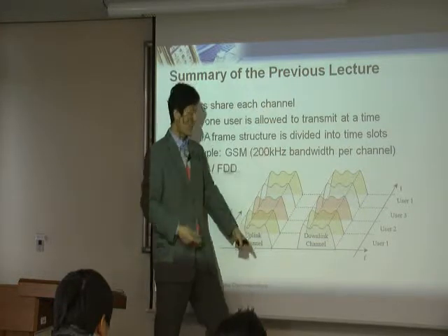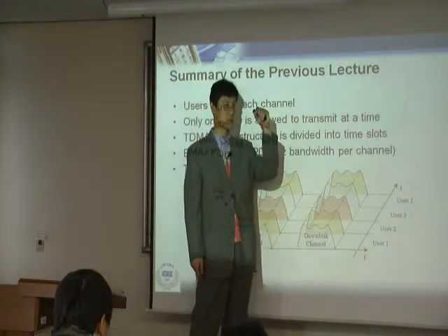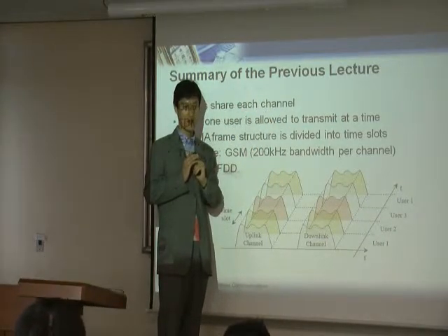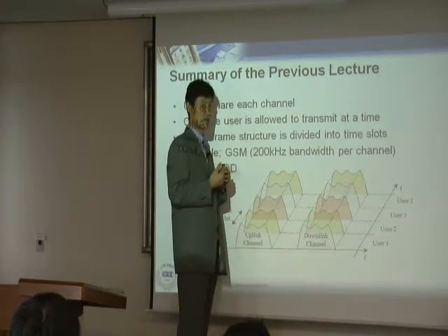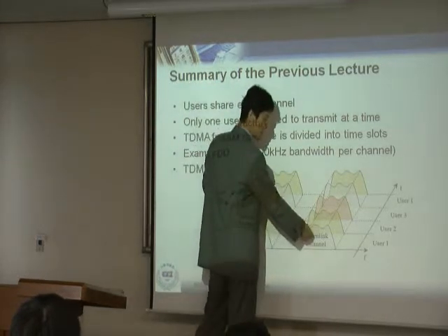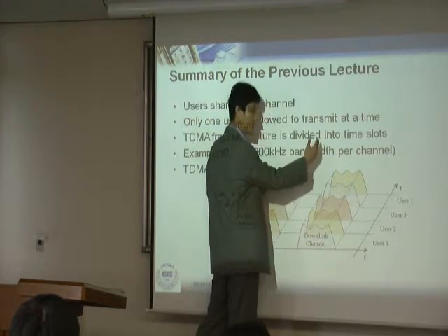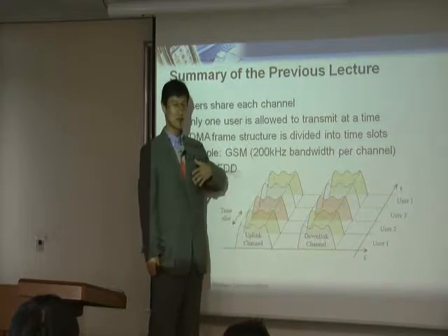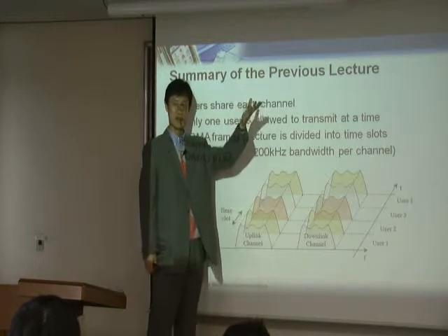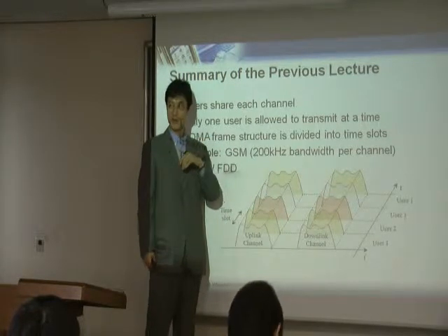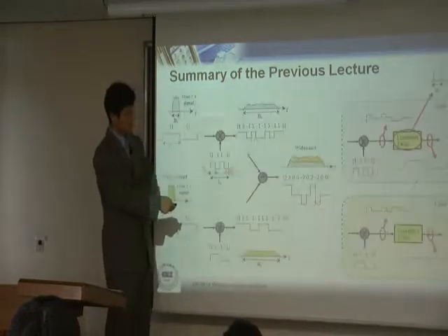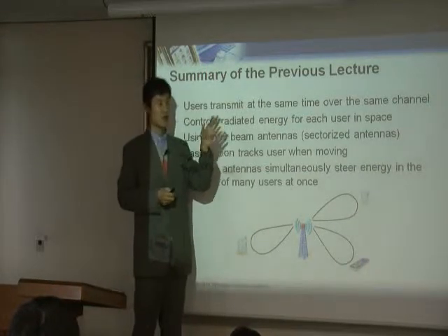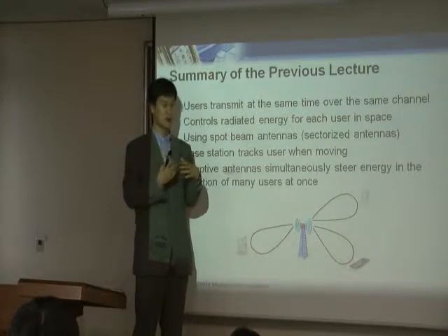at the base station time. However, in downlink, the base station transmits, so after a little bit of propagation delay, you receive it. So from the base station time, my downlink time is actually a little bit later than the base station time. My uplink time is a little bit ahead of the base station time. Which means that you have to do the synchronization of downlink and of uplink independently.